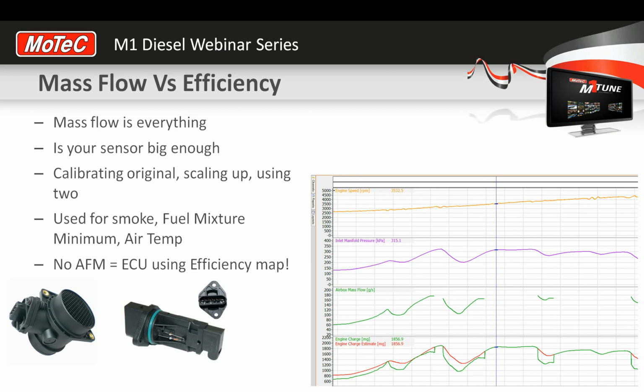So in the diesel project, we actually have a channel you can view for the lambda estimate. That is what the ECU thinks the current air-fuel ratio is. It does that calculation based on the amount of fuel it thinks is going in and the amount of air it thinks is going in. I know we keep talking about this, but we're back to injector calibrations. If we had dead accurate injector calibrations, then if the lambda was wrong as we were tuning, the only reason would be that the ECU's calculation of airflow was wrong.